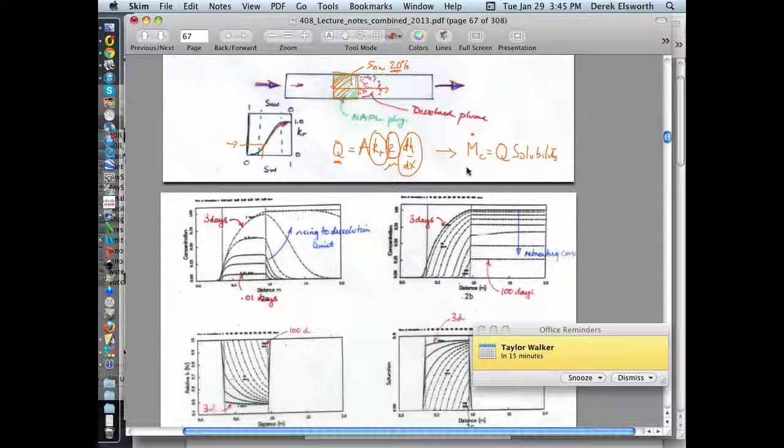And so, if you know the rate at which you're removing fluid from here, you'll know the rate at which this saturation will decrease. And if you know the rate at which this saturation decreases, you know the rate at which you'll move down this curve here to be able to look at the relative saturation. Actually, it's not here, right? It's going to be here. So this is 20% saturation of the NAPL, 80% saturation of water, and you'll move across to this point to get 100% saturated water. So you should be able to calculate the evolution of that.